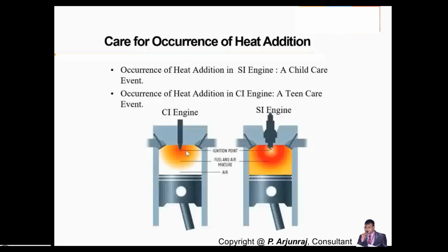But those additives will also have an impact on clogging the piston. Also, sometimes it clogs the air-fuel path, and it creates a stopping point for the mixture as well. It leads to a clogging effect. It has both pros and cons. You can even reduce the compression ratio. But one advantage is that since the piston speed is going to be higher, you have a shorter delay period, and the engine also reduces the noise.